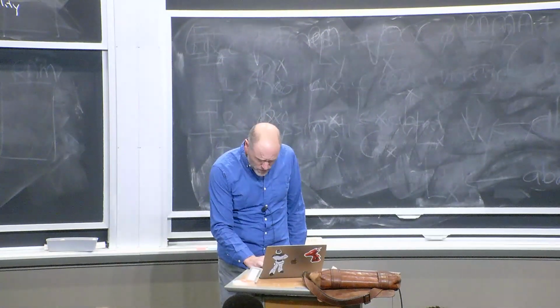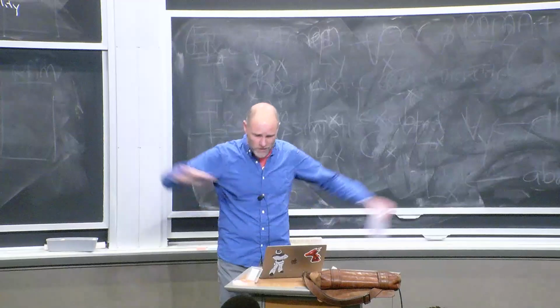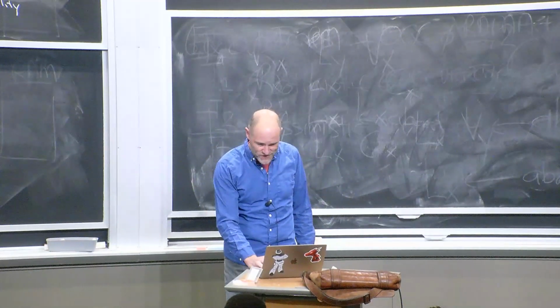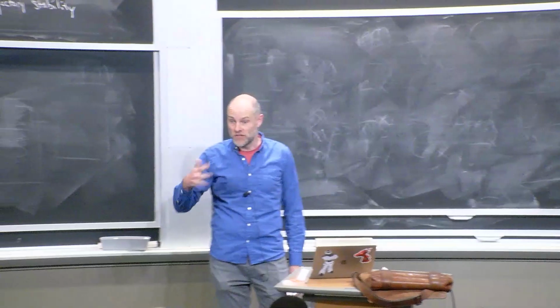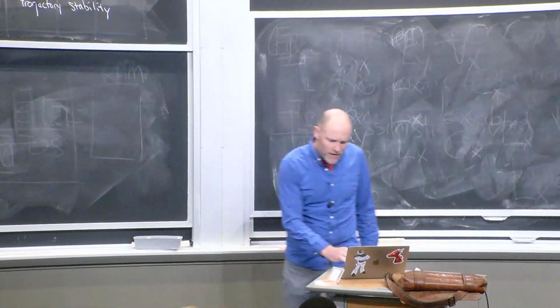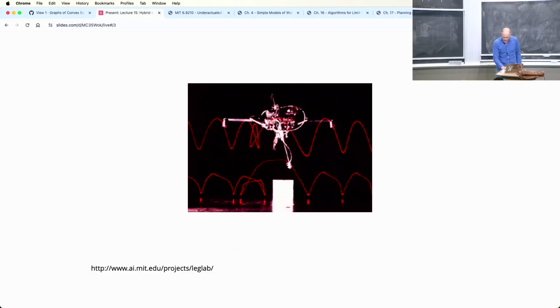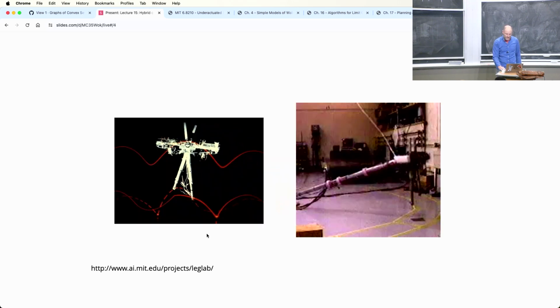But you'll notice that there's a long body with weights on the end. That's to give the body relatively a lot of inertia relative to the leg, okay? And there's a hydraulic control system that's actuating the hip, but a pneumatic one in the leg, because you wanted an air spring in the leg, okay? And it was just a beautiful, simple design.